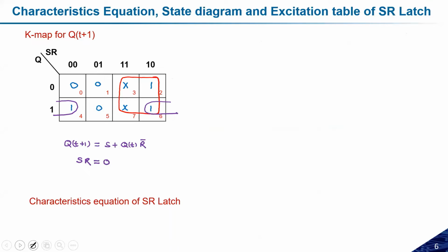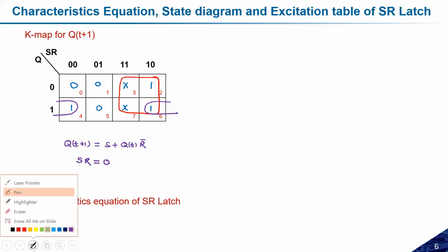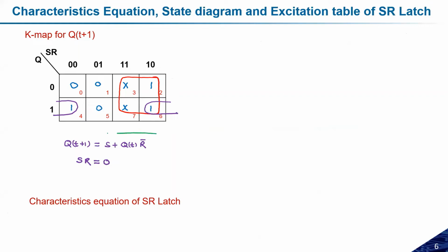Yes, please, does anyone have any doubt? Okay, fine. This equation that we are seeing here is really very important, especially if you will design counters and other things. Now let us try to see a few more things. These two equations, we call them the characteristic equations for the SR latch.